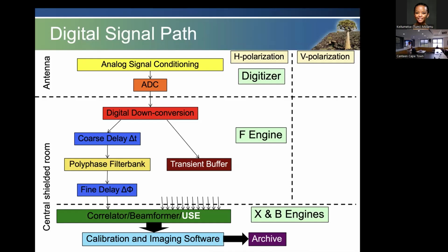In the old days, before Fourier transforms and FX correlators, we used to have XF correlators, which were real correlators. This is called a complex correlator. The Cambridge correlators and everything from before were real correlators. They did the correlation, but they did the Hilbert transform by doing a 90-degree phase shift using basically an RC network.